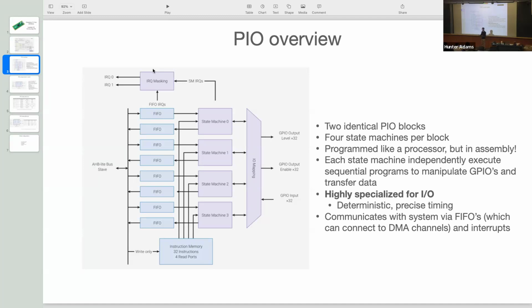The more powerful way to interact with these things is all of these FIFOs are visible, they're all memory mapped, and so we can point DMA channels at any one of these. And so if you have a DMA channel facilitating communication between these state machines back to whatever process you're running, the bandwidth that you can achieve between state machines and your application code is tremendous. You can, at very, very high rates, shuffle data from memory, say a pixel array, over to a state machine that's running, say, a VGA driver. Right? So you could have that DMA machine shuffling stuff over at 25 megahertz. Or alternatively, if your state machine is sucking information in from the GPIOs, you could be retrieving that information extraordinarily quickly.